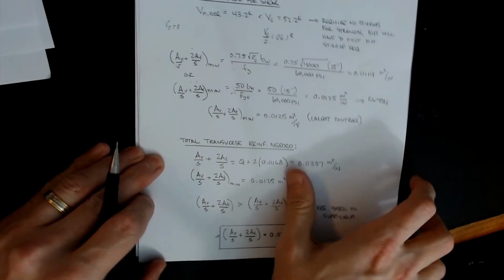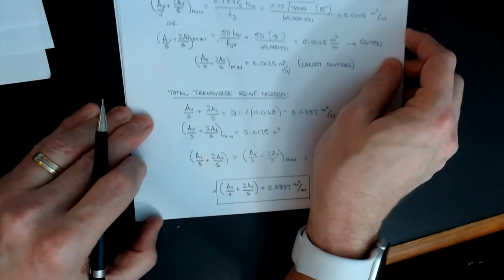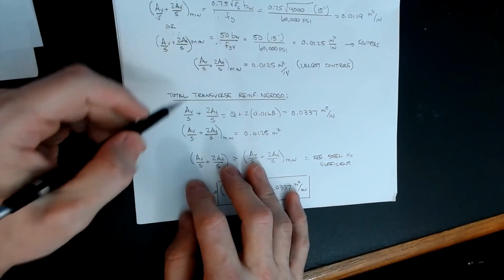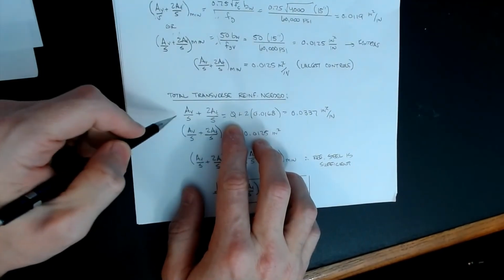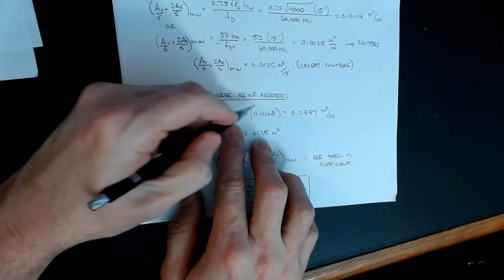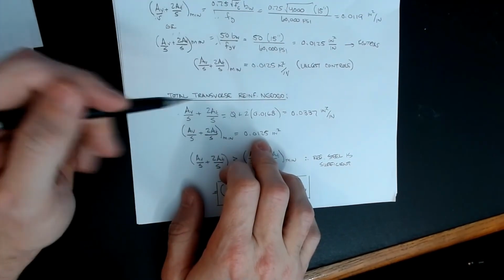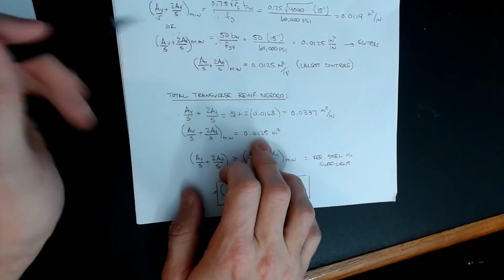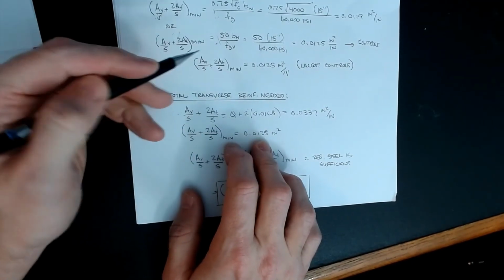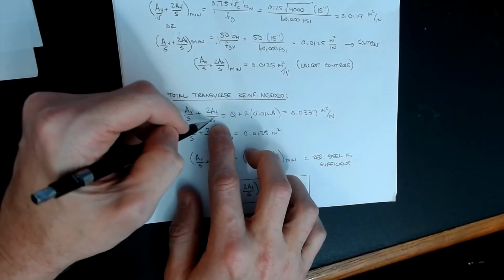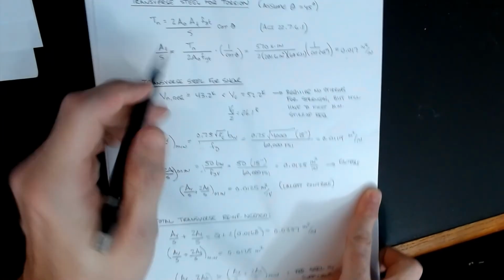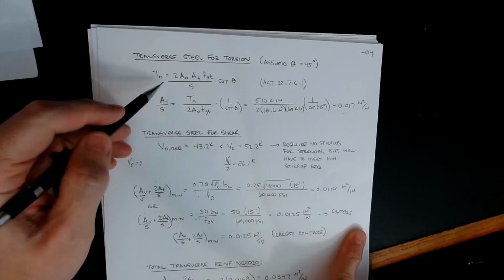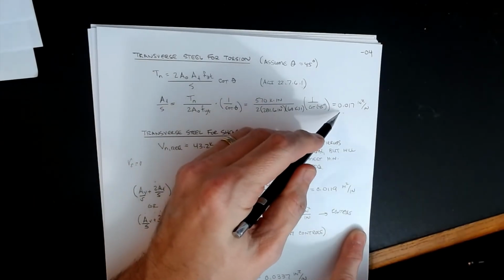Okay, so if we look at the total transverse reinforcement needed, well, let's go look at what strength told me. Av over s plus 2At over s would be equal to 0 for the direct shear. So the first term is the direct shear, the second term is the torsional value. Okay, and because it's a closed stirrup, we only count on 2 of the legs for the torsion. So we said that the At over s value that we needed in my original calculation was up here at 0.017, right? When we did the calculation for the strength. That's coming out of this Tn formula. Okay, so that's what I needed for torsion as At over s.